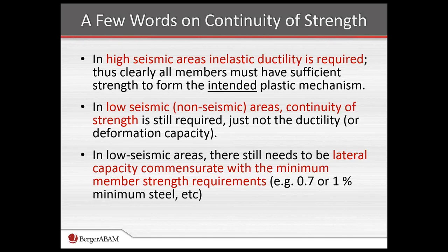will lead to a lateral capacity that we can mobilize the strength of, let's say, the column, the cap beams as a lateral system. The same would be true for lateral design, say, for wind. You need to be able to certainly resist those lateral loads, even though you may not be counting on inelastic deformation capacity as we would in the higher seismic areas.